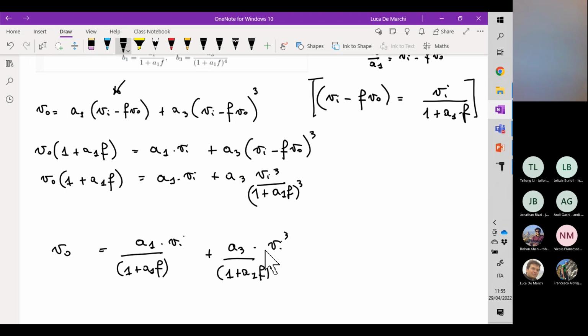And basically, the reduction in the gain is totally equivalent to the increment in the bandwidth. Okay. So since here we have a minus 20 dB per decade curve, we are moving along this curve to the corner here, okay?